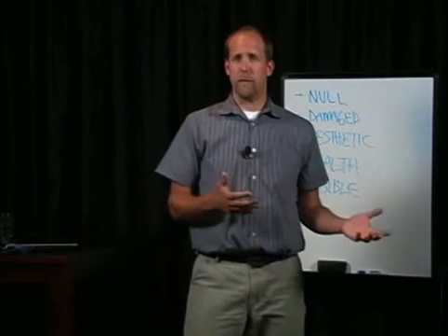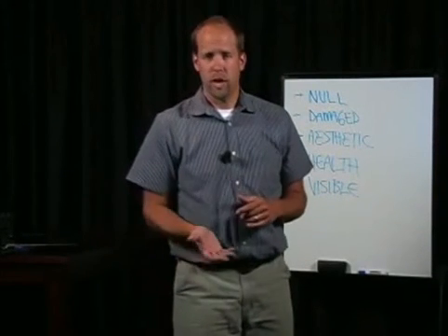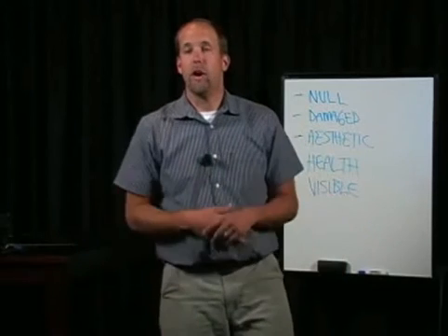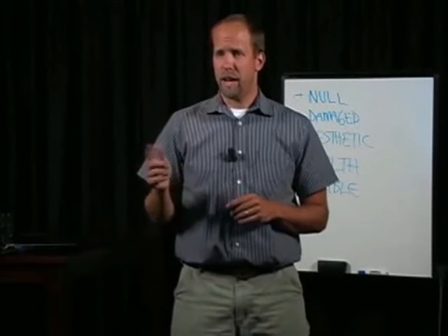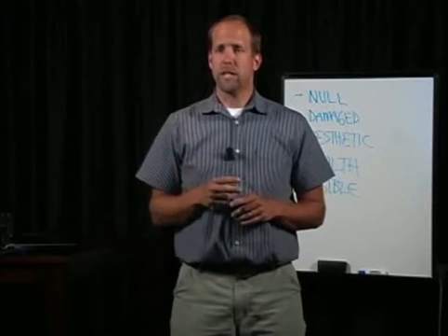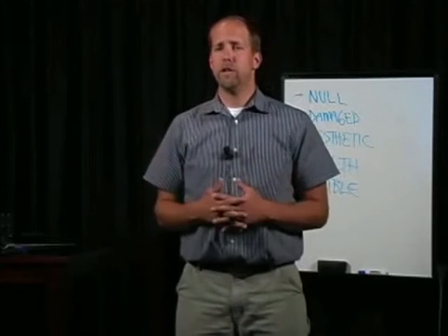So, the initial hypothesis that there is no mold growth at the building that could affect the occupant's health, cause structural damage, or produce odors, and there are no conditions conducive to mold growth, was disproved and found to be false. The evidence outlined in support of the three assumptions or additional hypotheses that the apparent mold growth is in fact actual mold growth, enough moisture exists to support mold growth, and mold spores are floating in the air, are sufficient to conclude that the source of the excessive moisture in the basement should be corrected and the water damaged or mold contaminated wall material should be replaced.